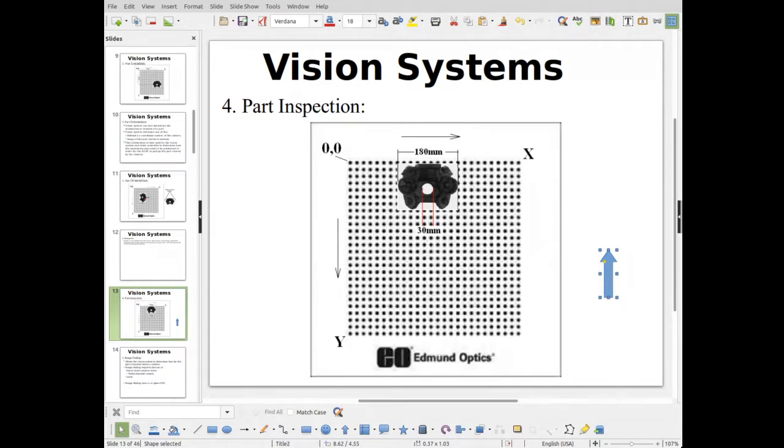So again, it can use the same calibration that the orientation and position things use, and so you can really kind of do all of those, right? With the exact same camera, we can do all of these that we've discussed so far with that one camera sitting in that one spot and just taking that picture. Okay. Now, one thing I forgot to mention about this grid, I want to make sure I do mention, is that once you've calibrated the camera, the grid is no longer needed. Okay, it doesn't need to look at those dots every single time.